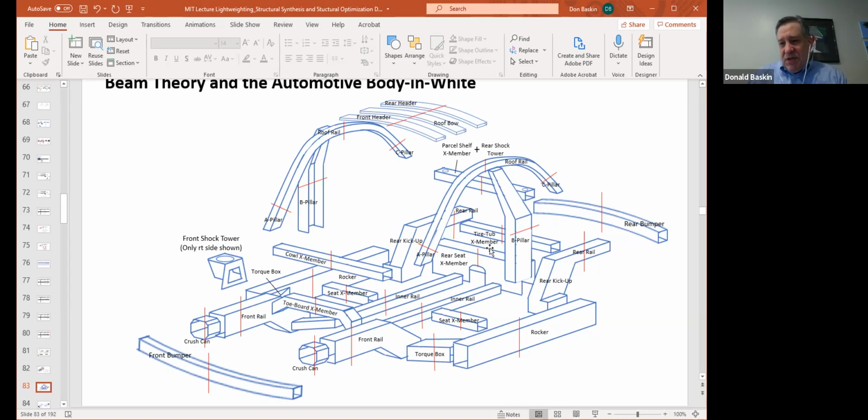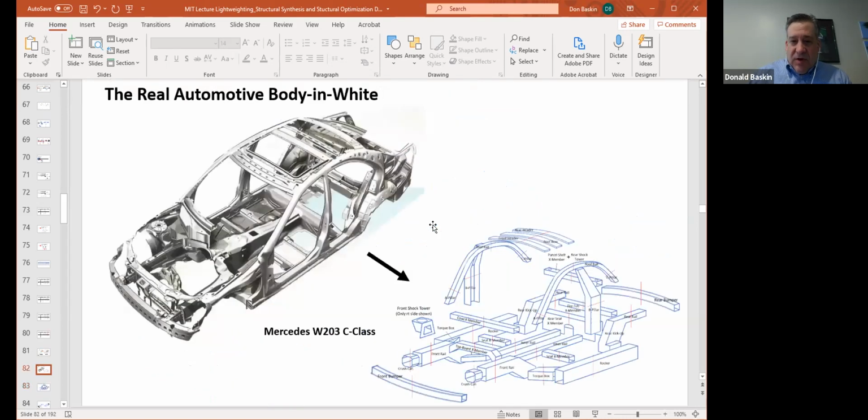The jargon that's used in the auto industry, just so you know, is A pillar, B pillar, C pillar. Okay, the A pillar is this pillar right here. This is where you look out when you're taking a right turn, or a left turn, you'll look at this A pillar. This one right here where the front seatbelt mounts is the B pillar, and then the one right back here that blocks your view when you're switching lanes on the freeway, that is the C pillar, okay?